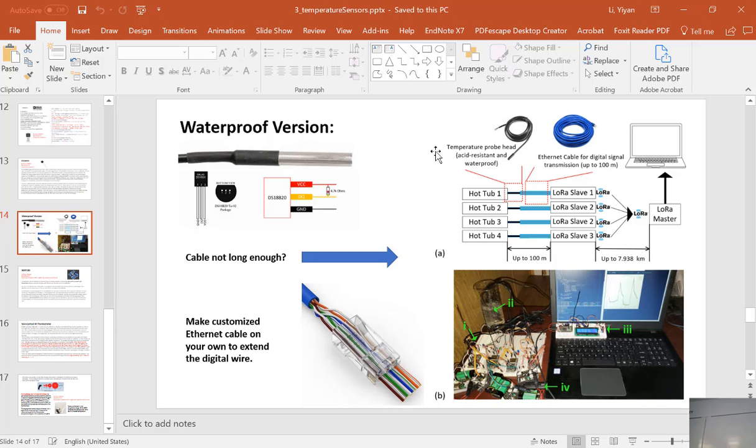So I have to connect the plus and minus. There are three wires: plus, minus, and data, I2C. But you have many cables here, and you just need to use 3 of them. Just pick up 3 of them. It's not sending internet data, right? It's temperature data. So we just need 3 of them, and then make a connection on the other end. And at this end, plug this one into a female header on the embedded system you have, and read it out.